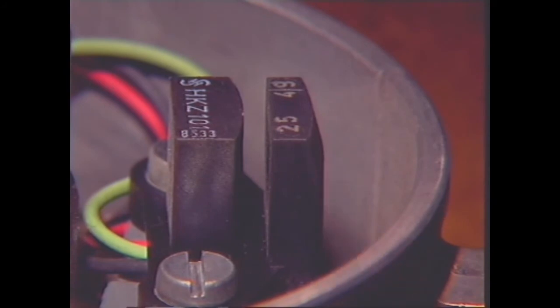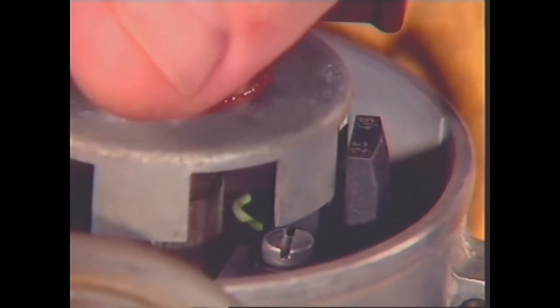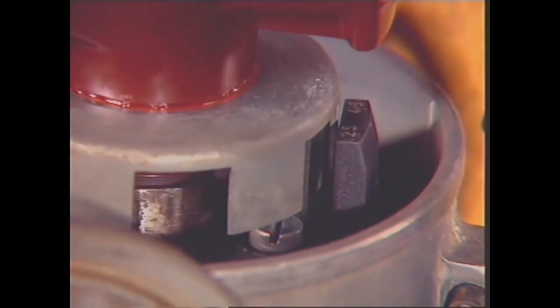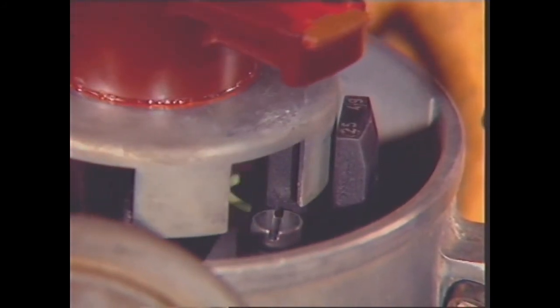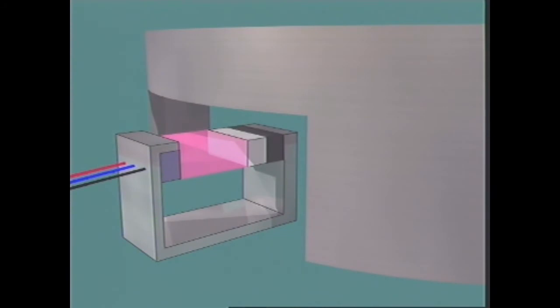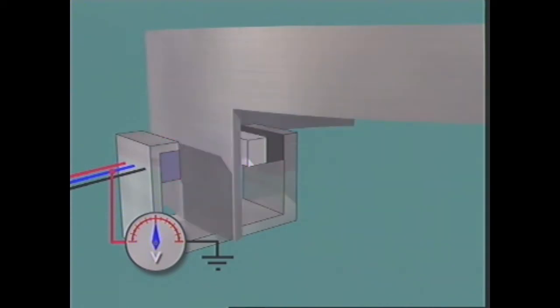An interrupter ring, which has the same number of blades and windows as engine cylinders, is rotated by the distributor shaft, moving the blades through the air gap. When a window is aligned with the assembly, the magnetic field is at its strongest, and its lines of magnetic force permeate the Hall generator and its integrated circuit. This allows the generator to switch to ground the low current signal voltage applied to it. When the interrupter ring rotates so that a blade aligns with the assembly, the magnetic field is shielded from the generator and the signal voltage is not switched to ground.